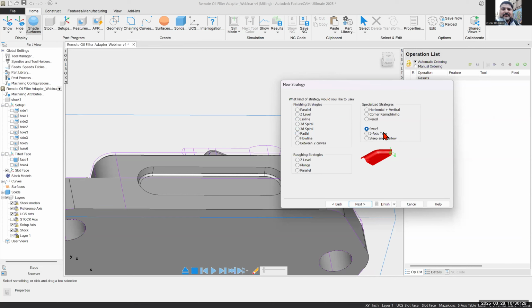And what that's basically going to do, it's going to take the geometry, and this has to be top rail and bottom rail of the surfaces that I choose. They don't have to exactly have the same shape, but the surface between them does have to be planar at the given point of the orientation of the tool. In this case, we do have a nice flat surface. There's no bulging, there's no gaps. So the end of the tool, the diameter of the tool can follow those surfaces very easily.